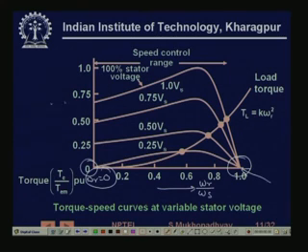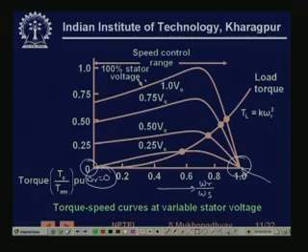Firstly, from that equation also you can determine that Vs has a rated stator voltage for which the motor has been designed. Motor is designed for a particular voltage, its insulation is designed to withstand a particular kind of voltage levels, plus its magnetic design is based on a certain level of flux flowing, which is decided by the supply voltage. So, this is the rated voltage, 100%. Now, typically we are not going to increase its voltage beyond its rated voltage. Typically when we do control, we can reduce it below, but we cannot increase it more.